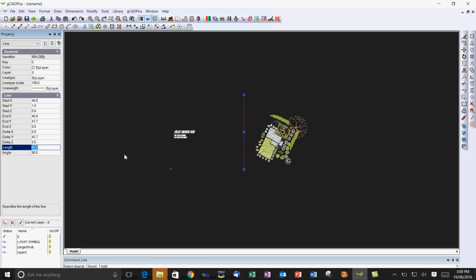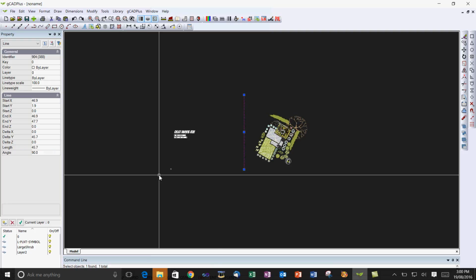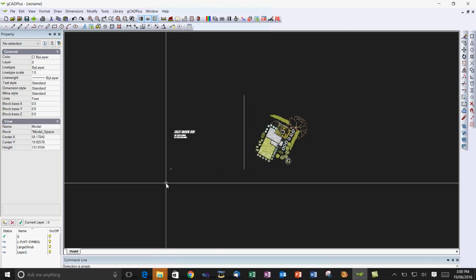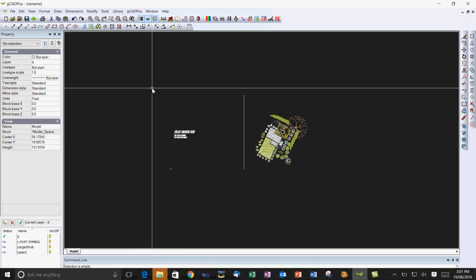So clearly in a CAD drawing, 0 is to the right, 90 degrees is up, 180 would be to the left, and so on, just like a protractor. So you can get lots of information about your design just by clicking on individual entities and using the distance tool that we've used several times.